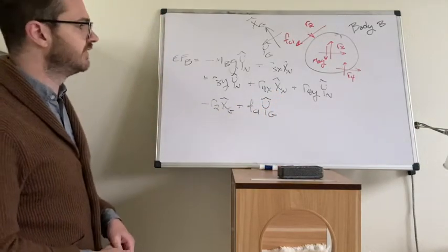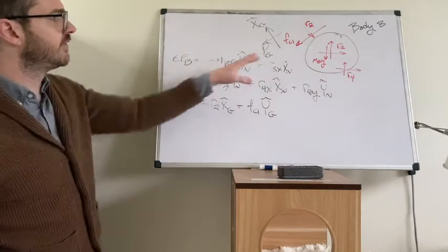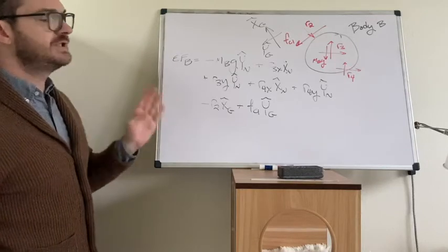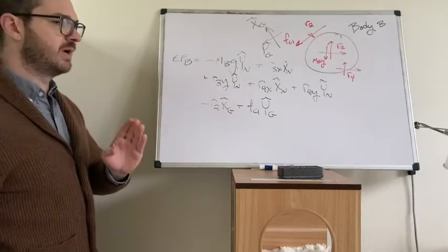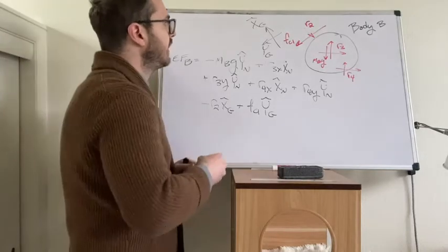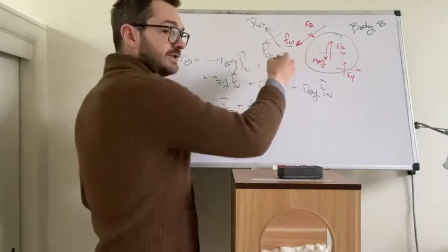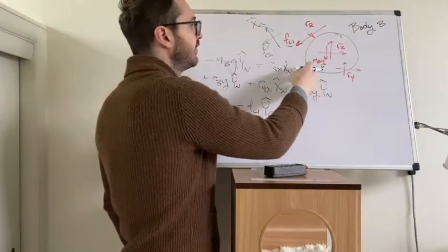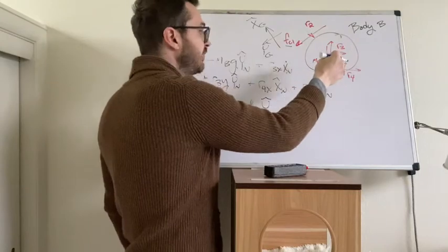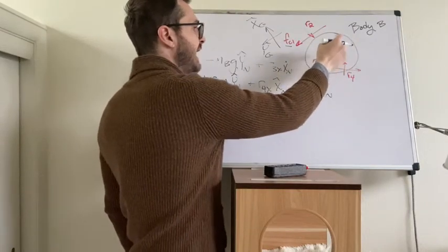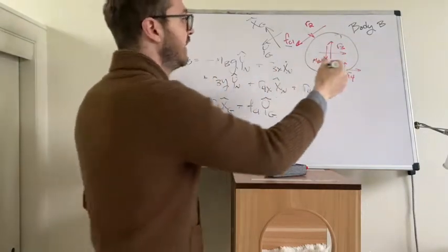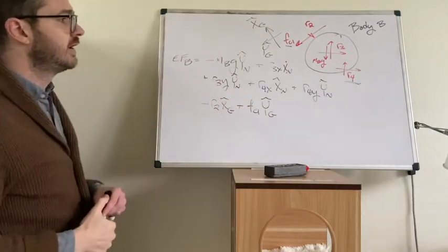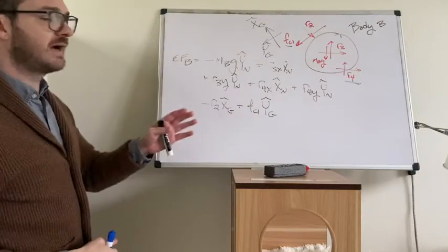Okay, that's literally it for the sum of forces, right? You just go from the diagram and you copy everything in. Next, which of these forces create moments? Well, the friction force is going to. R2 is pointed at center of mass, R3 acts at center of mass, and MBG acts at center of mass. So again, those don't. However, R4, reaction force number 4, both of those create moments, the R4x and the R4y.